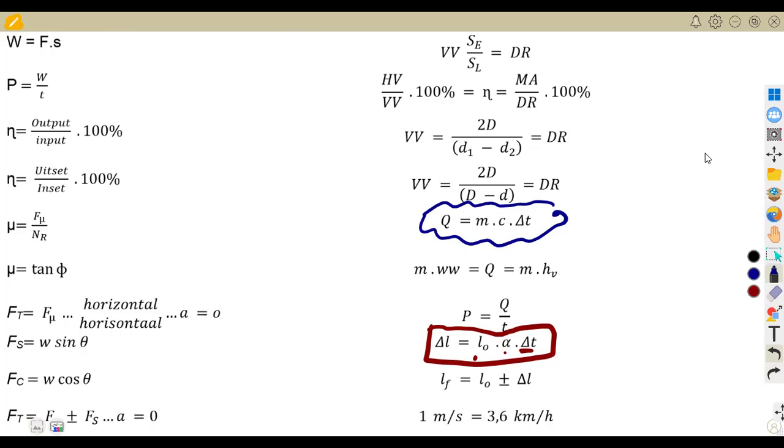It can be for steam, whatever you can be given. Maybe it can be of a metal, talk of copper, aluminum, steel. Then where we have a heat value, here Q is equal to mass times the heat value. This one uses the heat value, meaning when you're talking about something like petrol, or coal, we have the heat value. So you must know where to use the formula. This one is best where there is a heat value for that particular object.